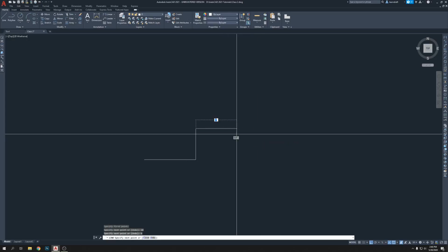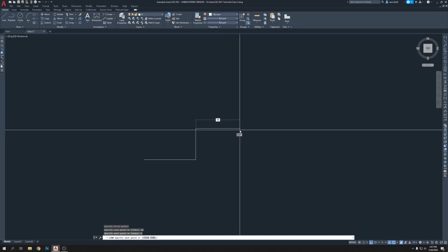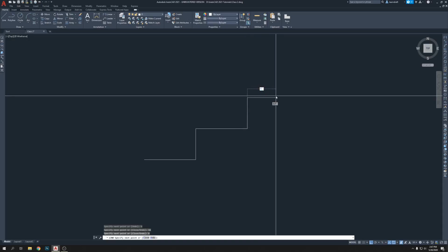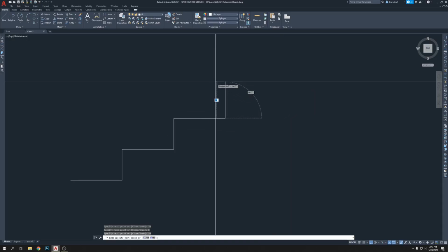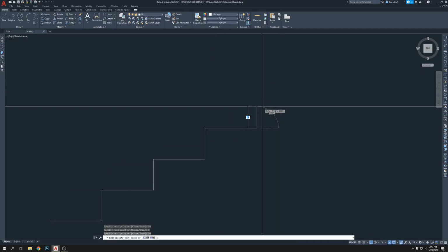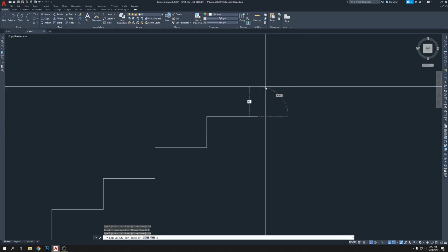If you want to put it in feet, then you type feet, which is the key next to your enter button on your keyboard. Foot and inch there. So now this way 10, enter, go up 6, enter, then go 10, enter, then go up 6, enter, then go 10, enter, then go 6, enter, then go 10, enter, then go 6, enter.